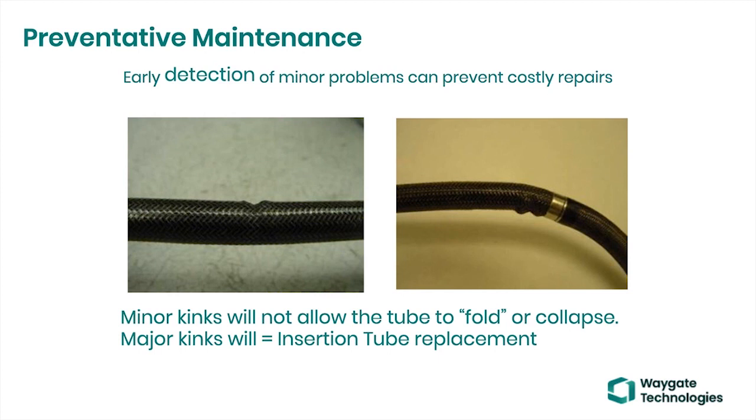Tom, I think that is a great idea, and I'll address it now, but I'll also address it more thoroughly in about 2 slides. So what Tom is referring to, if you're looking at my screen right now, I'm showing you on the left-hand side an insertion tube with what one might think of as a minor kink. Well, that braiding that you're seeing is a tungsten braid, and it is impregnated with polyurethane, and that is what creates the water tightness. In other words, this allows you to drop this assembly into 1 atmosphere or 30 feet of water, and it is watertight.